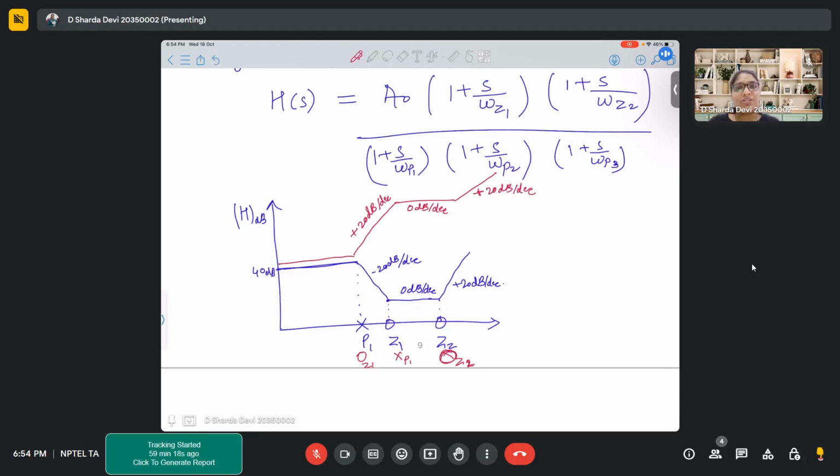So in the lab also, when you are performing output impedance analysis, you'll use a test source, and you will give your VDD and ground rail to the op amp, but whatever input sources are there will not be provided. Rather, they'll be open or grounded, depending on how they are connected. From the test source you will get the voltage and current, and you'll divide that voltage by current to get the impedance.